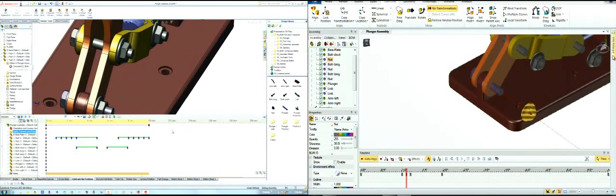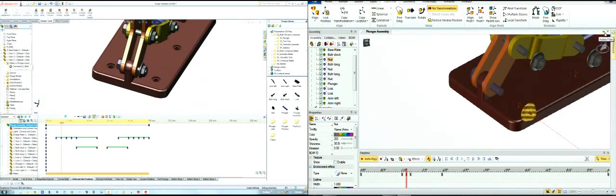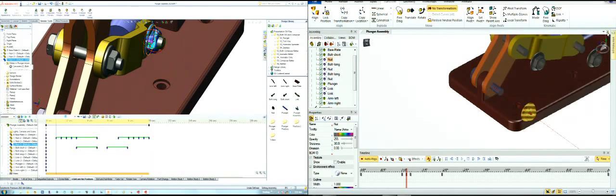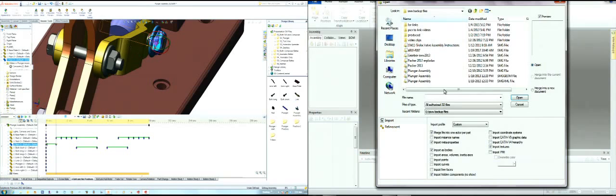So what we would wind up doing is very much the same thing. We would come out to some point. Let me just turn this off for a second. We can move with triad, and using the triad, we can first of all drag the nut out a little bit, and then we can grab one of the rings on the triad.